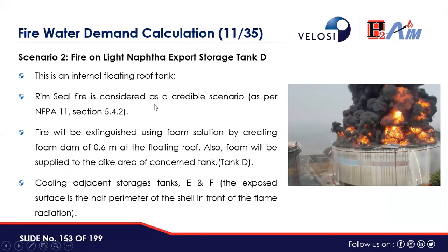Rim seal fire is considered as per NFPA section 5.4.2. Fire will be extinguished using foam solution by creating a foam dam at 0.6 meter at the floating roof. Also, foam will be supplied to the dike area of the concerned tank, which was D.